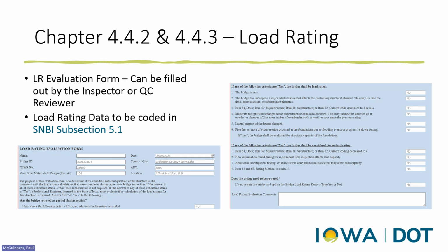In this case, if you look closely, you'll see they're all no's, so it's pretty obvious that this bridge will not need to be load rated. But it's important to distinguish, when some become yeses, does it mean that a bridge needs to be reload rated? And the answer to that question is not necessarily. It depends on which question is yes. And some may just trigger the need for a professional engineer or a load rater to determine if it should have a reload rating.